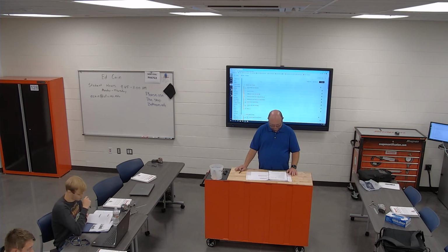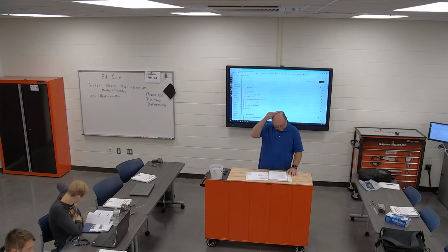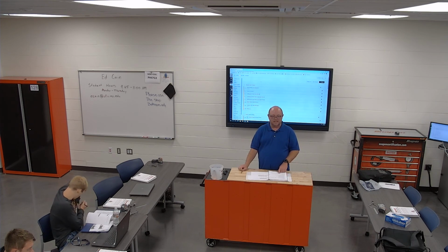So for, let's say it was 3/8-16. Well, the feed per revolution is 1 divided by TPI. The thing is, if you change that 100 to like a 200, you're probably wrong. It just happens to work out because the numbers we use, I would imagine. If I did a 3/8-16, then that would be 100 divided by 16, just 6.25.